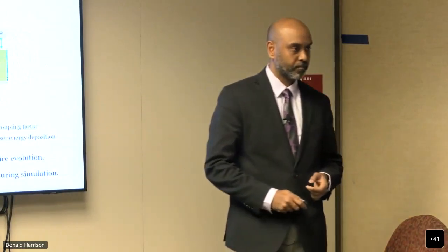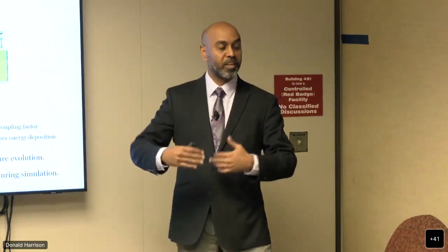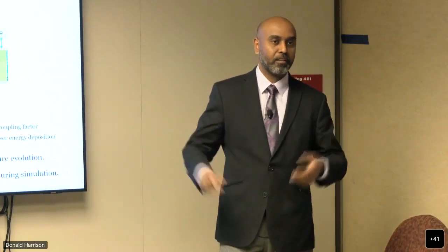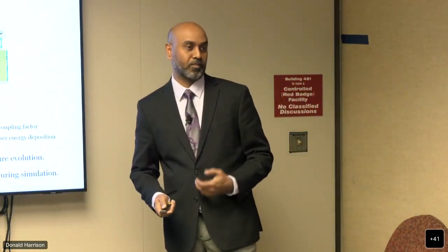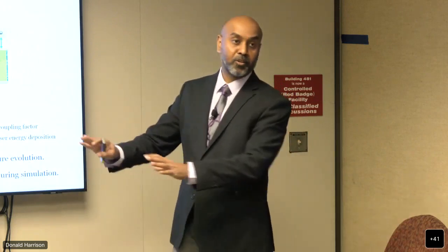You calculate the laser ablation? Yes. Given the source term, the model predicts whether or not it is going to ablate. That depends on how much energy is deposited. And we take into account the reflectivity of the metals as well. For aluminum, 90%, tantalum, 30%. And we can add that to the model.